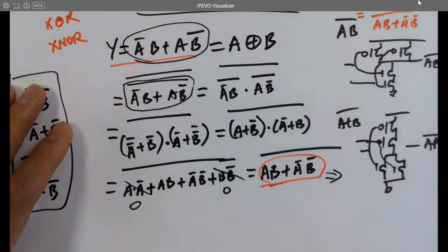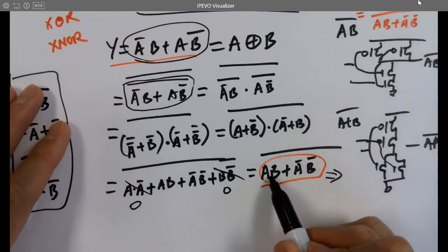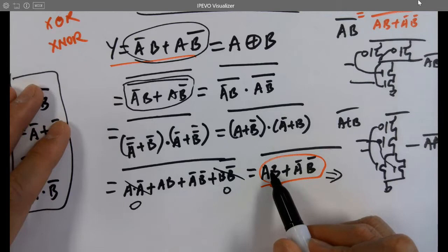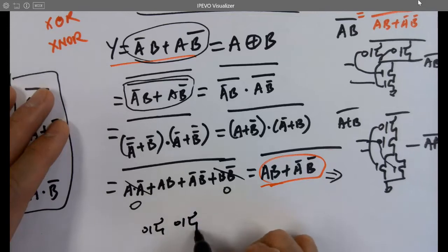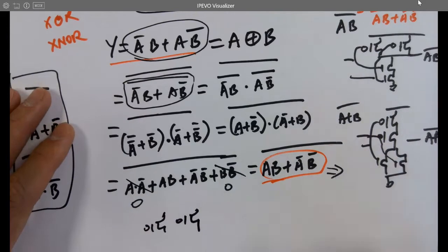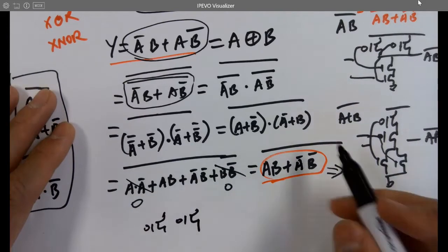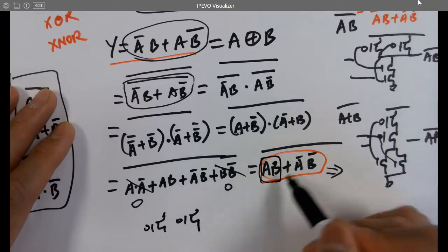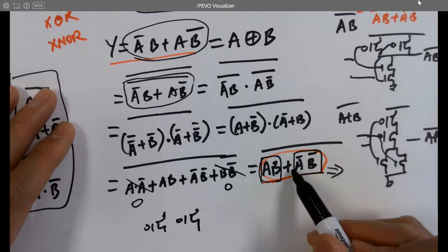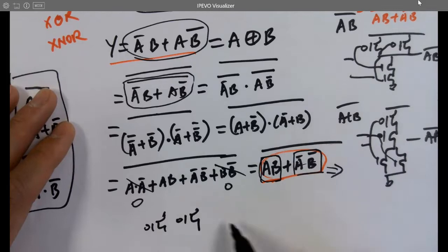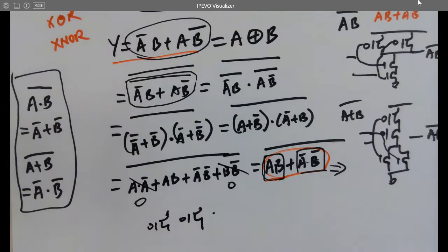I'll start with this one. Okay. AB is AND logic. So what do we need for these two inputs? Oh, yes, in parallel, right? Let's do the PMOS first. Start from the top. And if you treat this one as one entity, this one another entity, it's a NOR gate, right? It's OR logic. So need these two to be where? In parallel with these two, or just underneath in series? Remember the NOR gate? Always think about the NOR gate in series.